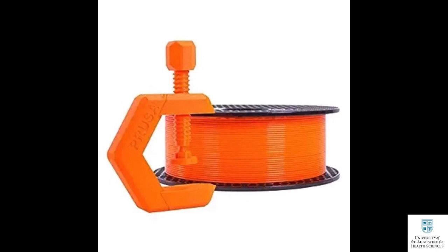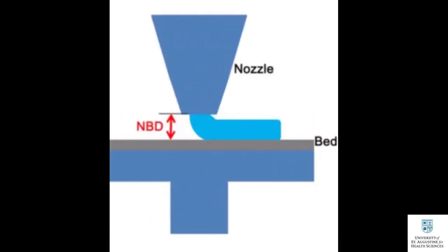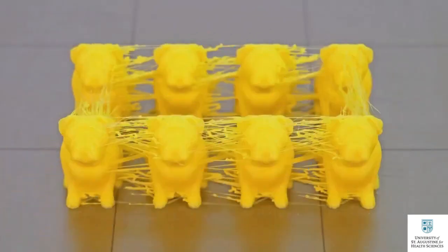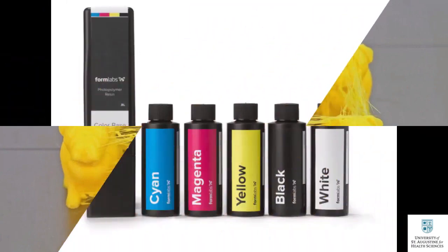However, it requires a high printing temperature between 428 degrees Fahrenheit and 482 degrees Fahrenheit, and a print bed temperature of 122 degrees Fahrenheit to 167 degrees Fahrenheit. It can absorb moisture from the air. It can become sticky when printed and scratches easily.